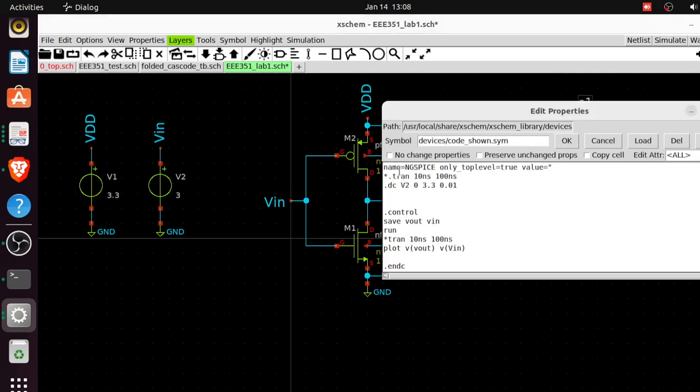So our first analysis, I think, we should do the transient. Like I told you, it's more or less like code you're writing. This asterisk here means I commented this out, so when the simulation is running, it won't see this transient analysis. To uncomment, I'll just remove the asterisk. I just want to carry out transient analysis alone, so I comment the .dc analysis.